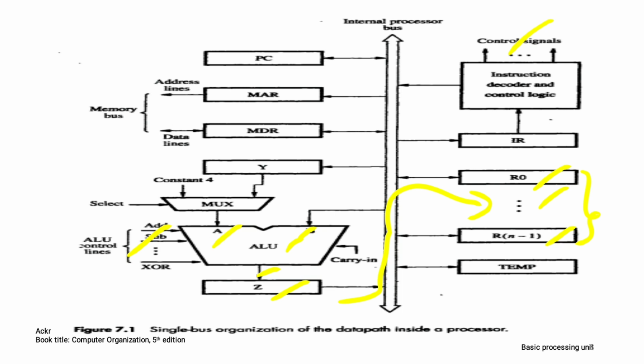The PC always stores the next instruction or next word address. If the processor is executing the present instruction which is stored at memory location 1000, then the next word address will be 1004. While generating the next word or next instruction address, this constant 4 is used.